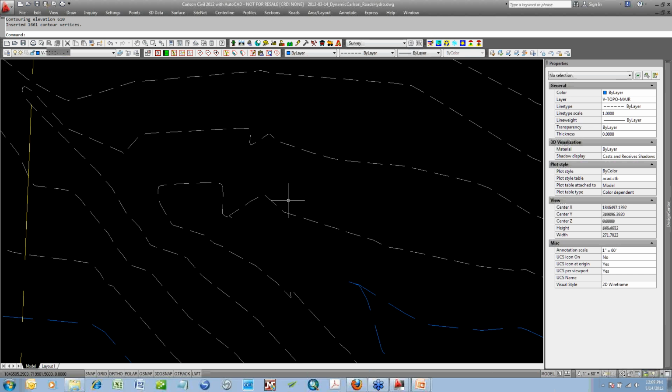You may have your points set for a proposed site plan. But when the contours come in, there's just a little kink or maybe a little hump or a bump in it that you'd like to smooth out a little bit. You can add break lines to do that, which again is probably the best way to do it. But when you get down to those very final tweaks, it's more for aesthetic purposes.